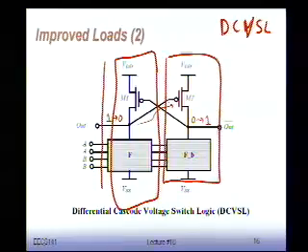But instead of grounding this, what we're going to do is cross-couple them. This is the first example of feedback we're seeing in this lecture, in this class. You can see that there's a feedback network hidden in here, one of them feeding back to the other one and going in a loop. Feedback will become very important when you start talking about registers.